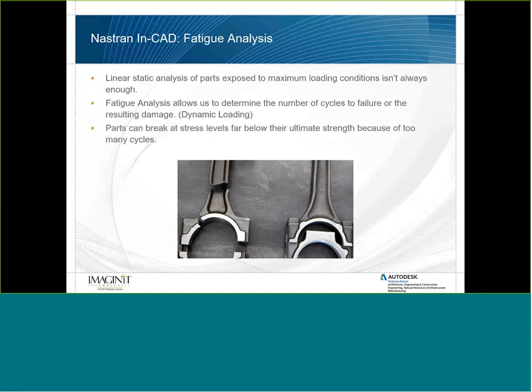So let's talk about fatigue. Sometimes we'll be looking at a design and maybe under our maximum load condition, everything looks fine. Our overall stress and displacement and safety factor results are showing values that we're comfortable with. We're not expecting to see any yielding or any damage as a result of our max load condition. But sometimes our designs are not going to be loaded at the max load condition in a static manner.